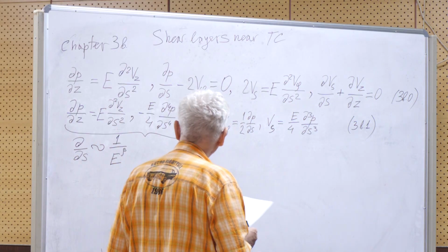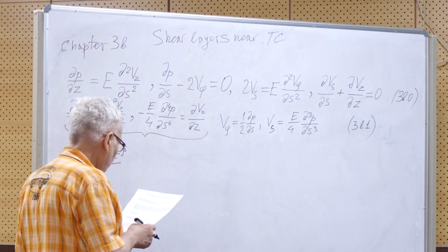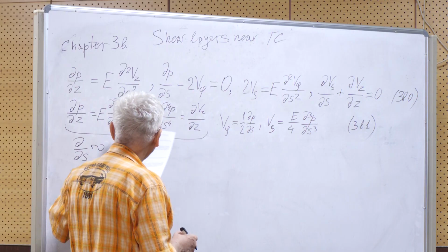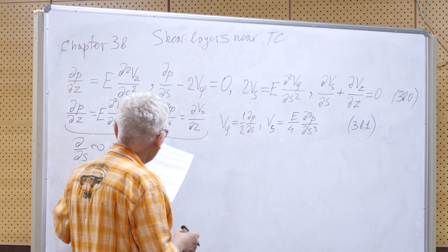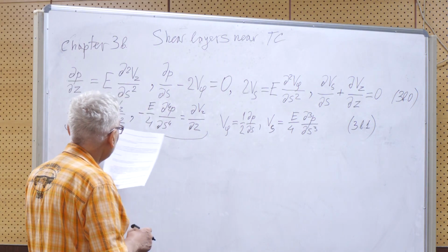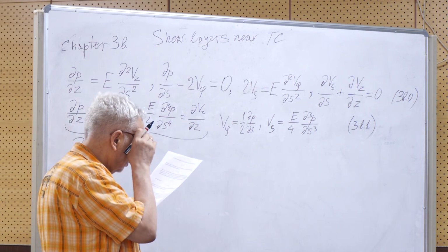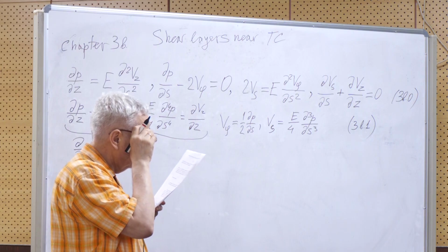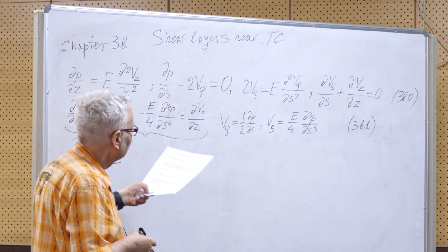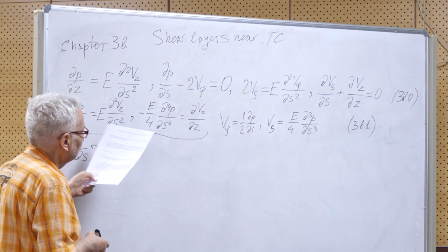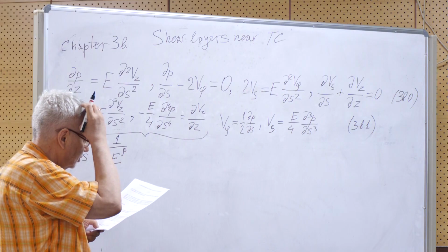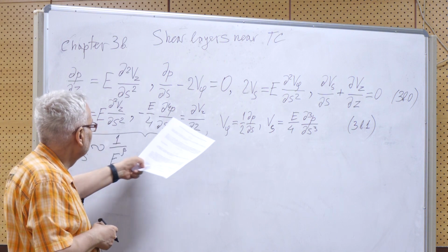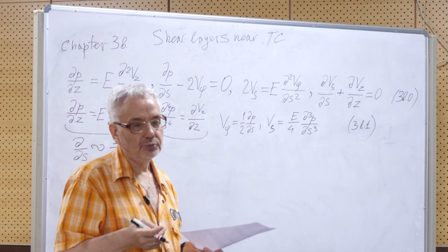And of course, we involve the equations to do that. So from the first two equations of 1, you see that there is a derivative with respect to the cylindrical radius that effectively works like this. And also there are some values which appear here. But anyhow, from the first two equations, we will assume that the pressure is related to the vertical velocity in order of magnitude. So these first two equations are the only important ones here, this is just a consequence. So we reduce the system, as I told you, just to two equations. And in these two equations, we have only two variables. One is the z component of the velocity, and another is pressure. Nevertheless, there should be some relation between them.